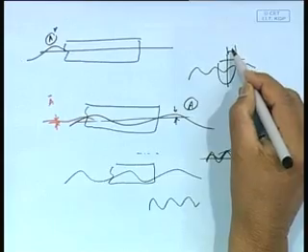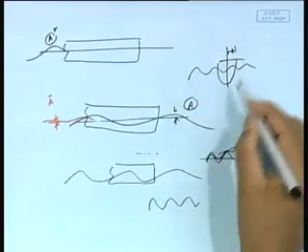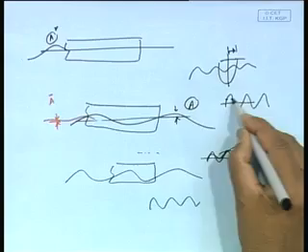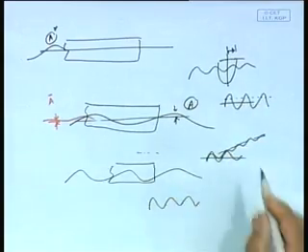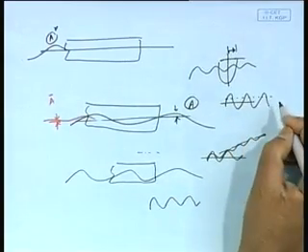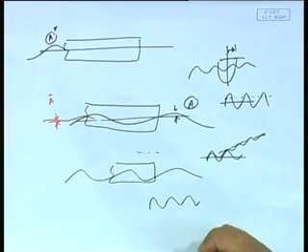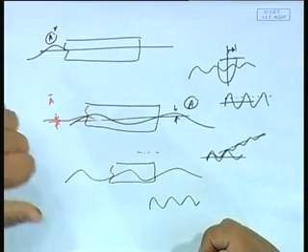If it was a first order force, it would have been oscillating. That means the force would have looked like that, but this force has a mean value. So, it would look as if it oscillates about a mean, which means there is a steady push. That push is equivalent to our added resistance. The physical hydrodynamic phenomenon is that push, which is what we call second order force, equivalent to our added resistance.